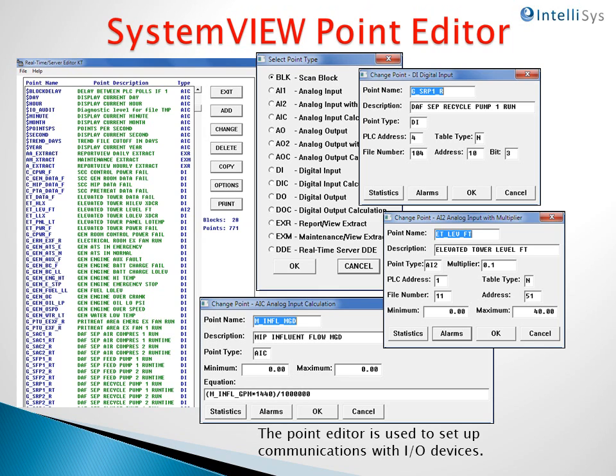The SystemVIEW point editor is actually part of the real-time server application. The point editor is used to set up communication with I/O devices. Various types of points can be set up in the system, and the block diagram on this view actually indicates analog inputs, analog outputs, digital inputs, digital outputs, units with and without scaling, as well as some special output for extracting to report view, extracting to maintenance view, and in this particular case, a link for a DDE device on the network.